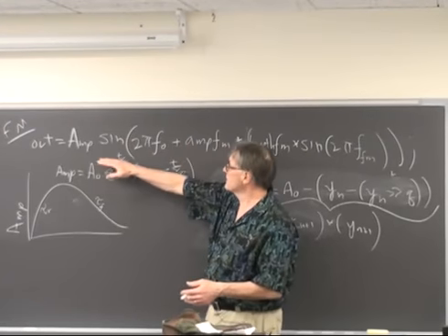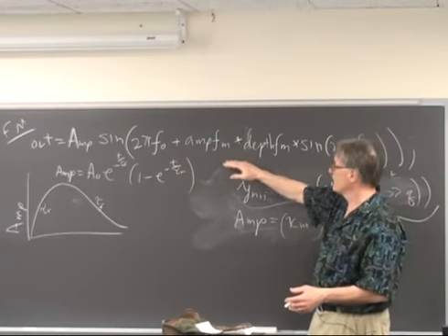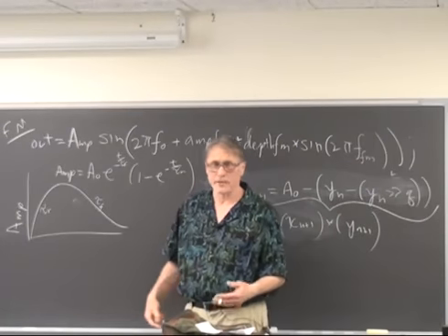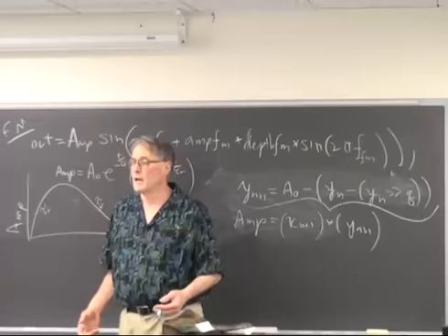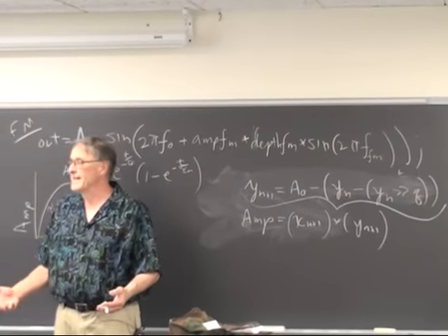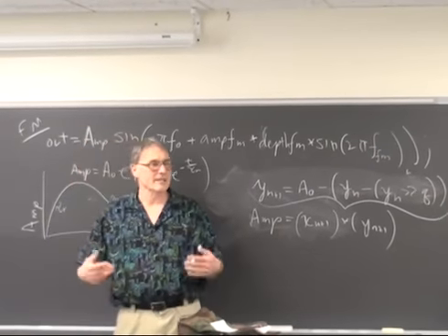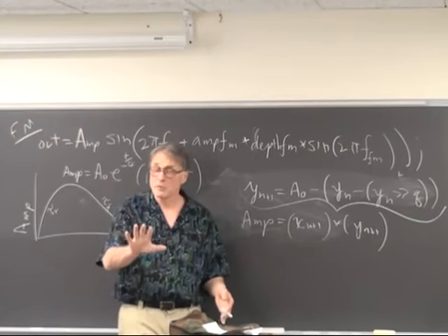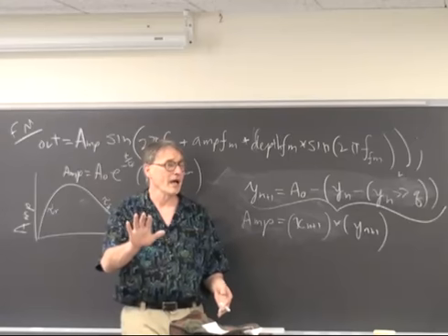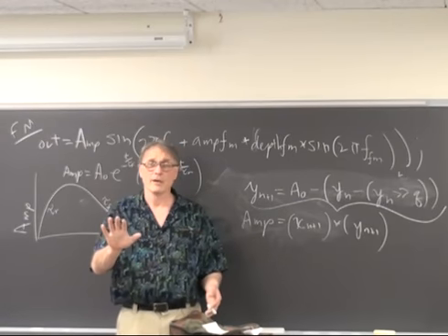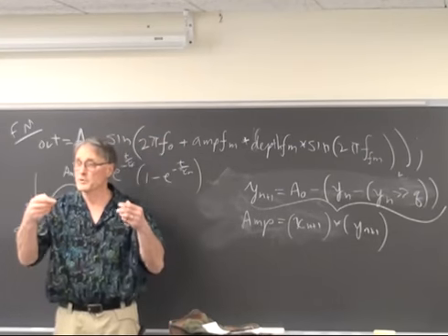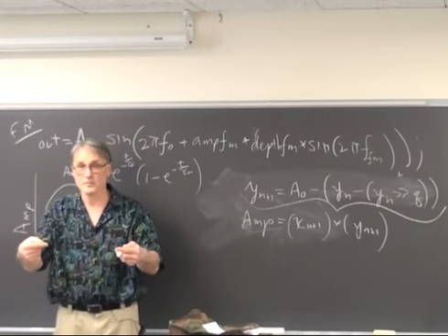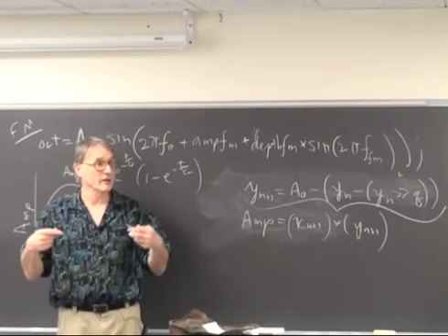So we take the nice, you could write this in MATLAB in one line. You calculate it out. It executes almost in real time on a 3 gigahertz dual core machine. And it's really easy. It's lines of code. It puts out a sound file, you play it. What I'm going to be asking you to do on the microcontroller is somewhat different. At every time step, at every sample time, every 1/8000th of a second, you're going to produce the next sample that's necessary of the signal, output it to the pulse width modulator, and then get ready to calculate the next sample.